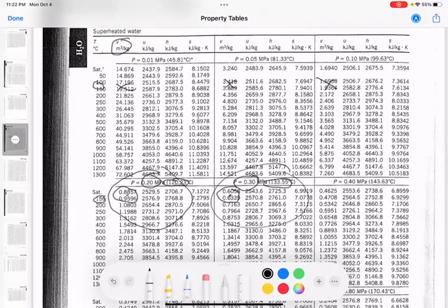But again, just to summarize what we're doing when we interpolate here, we're taking 120 and 150. Okay, we're linearly interpolating our way to 125 because that's the temperature they tell us we're at. So that's about a quarter of the distance from this guy to this guy, and that means that the specific volume there is a quarter of the distance between this guy to this guy.